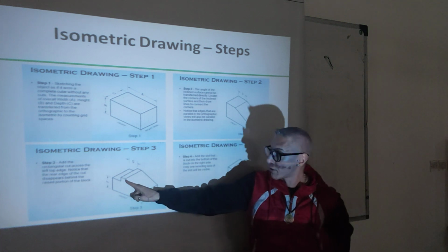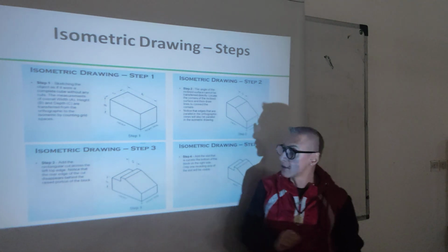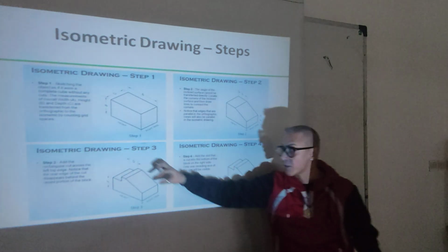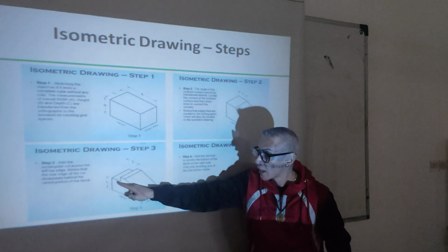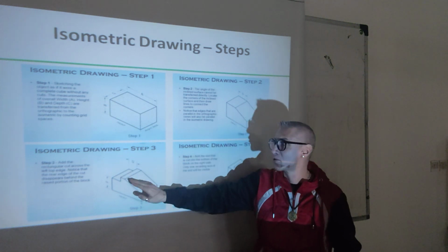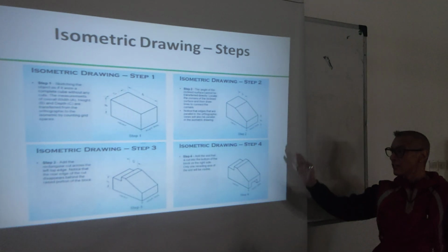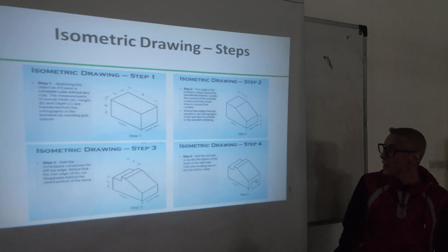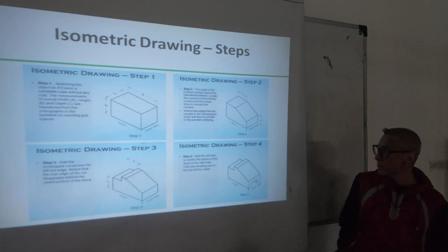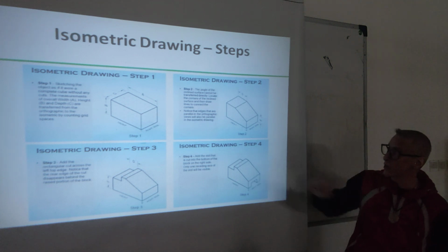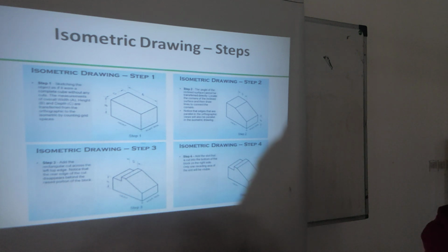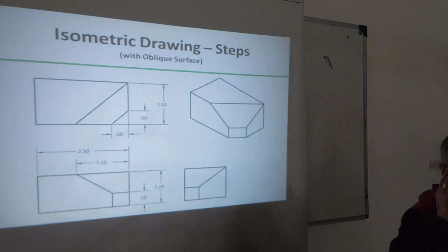After that, more of the details are drawn, okay? Again, taking measurements from the orthographic, and measuring here, all the lines at 30 degrees, don't forget, and later, any other left details, which is this part, an opening, also everything is measured and placed. So this is a very simple object, actually, but to illustrate the example.